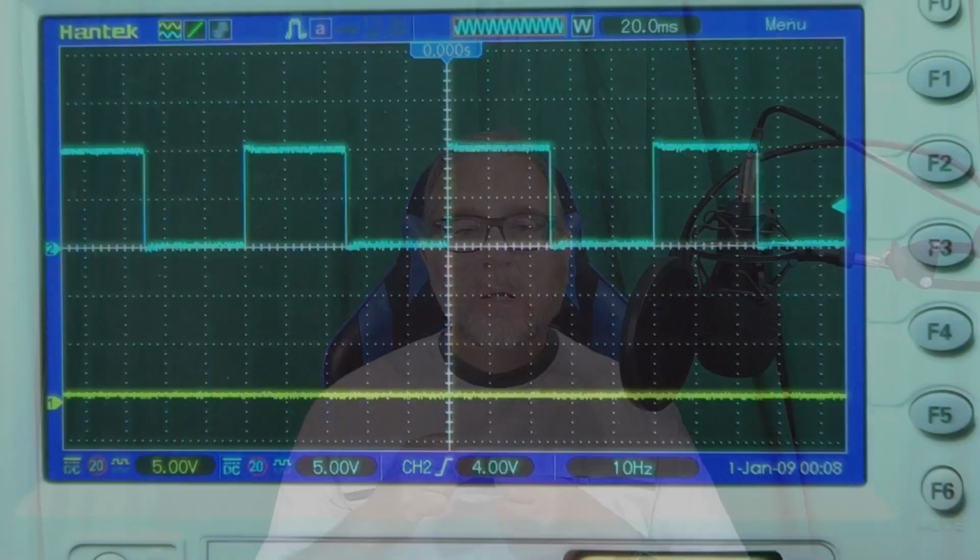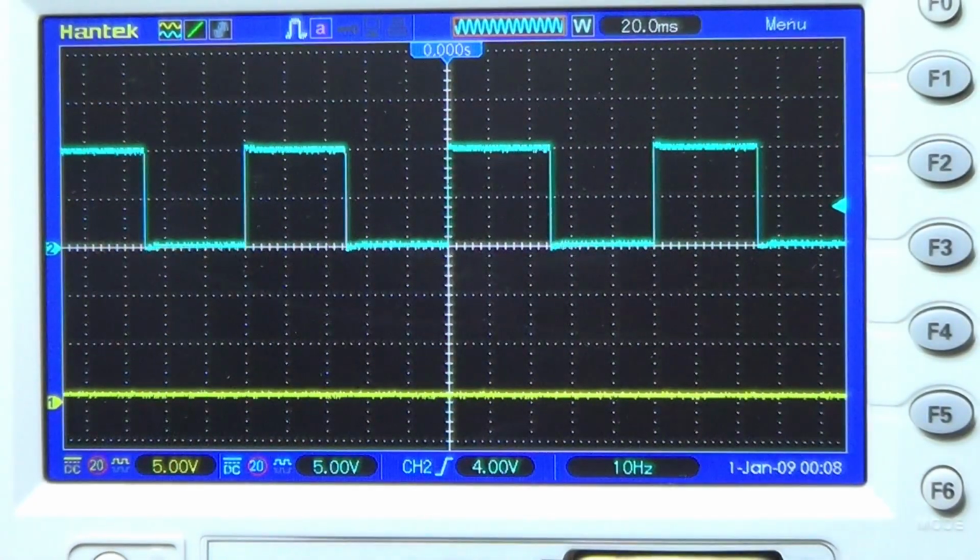Let me show now another interesting thing, the possibility of creating distortions of the control voltage when forcing the DC mixer into saturation, which can be done by applying an offset to the DC mixer while leaving the input voltage to the max value possible. So let's start by removing the offset and increasing the limitation to the max.